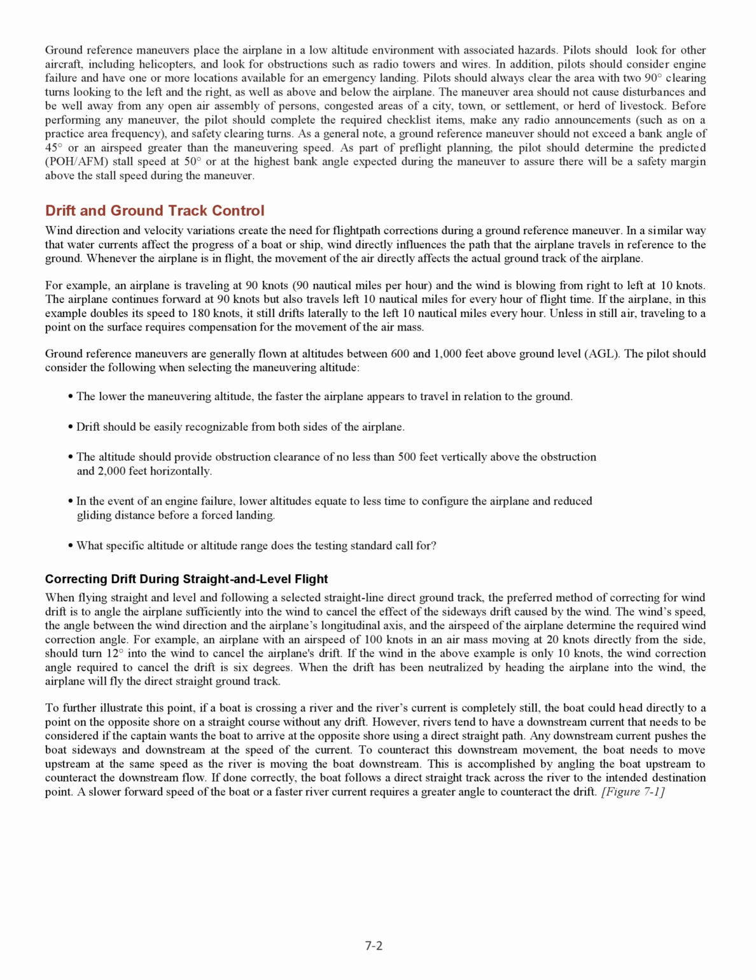The maneuver area should not cause disturbances and be well away from any open-air assembly of persons, congested areas of a city, town, or settlement, or herd of livestock. Before performing any maneuver, the pilot should complete the required checklist items, make any radio announcements, such as on a practice area frequency, and safety clearing turns.